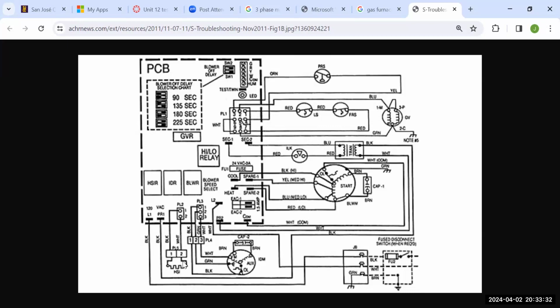So once your igniter glows for a set amount of time, next thing is you should get 24 volts at the gas valve. Then after you energize the gas valve, the flame should light. And your flame rectification sensor is going to prove the flame lit. I'm blind right now. Where's my sensor at? Let me right off of this.